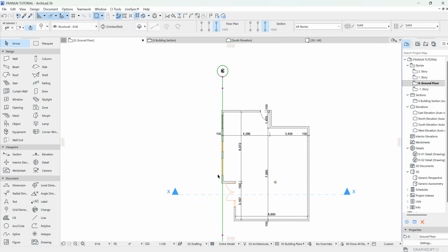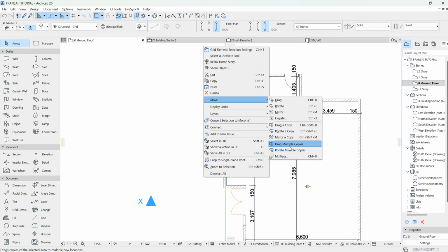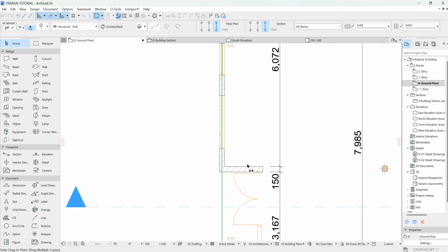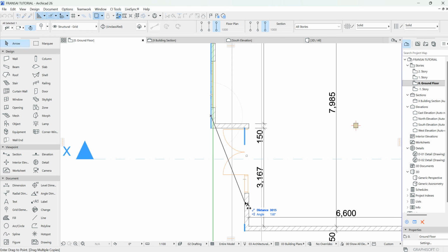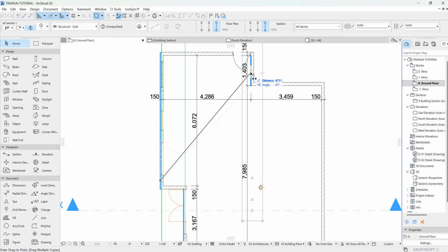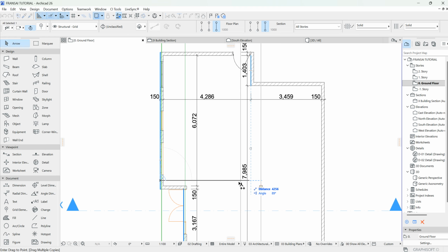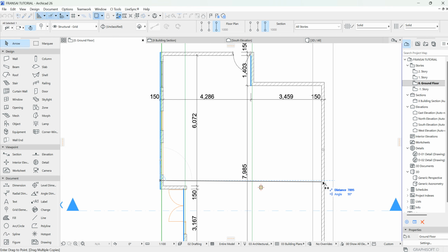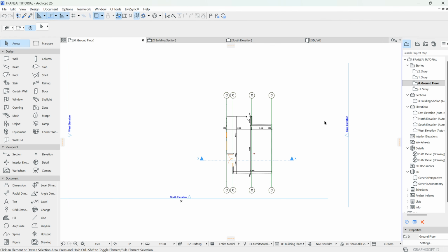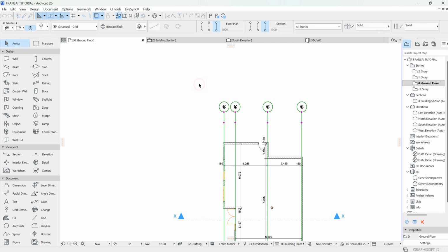So, what next do I do is, I want to duplicate it on all the vertical walls. So I will place my hand, you can see I can see the blue mark. So this is where I'm going to click so that I can actually place it on the edge of the other walls. That's the blue line. I follow the guideline out and the straight line and then I place it there. And that's it. So I've placed it on all the vertical walls.